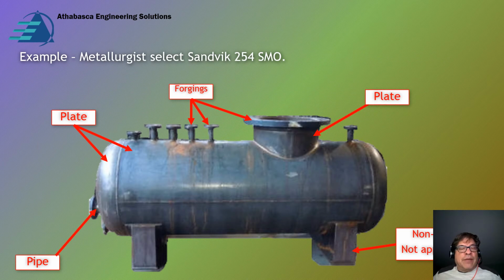We have our vessel, and we have to identify our product codes, and we call that the table I gave you earlier. So in some cases, our nozzle might be a fairly large nozzle. We might use a pipe, for example, and in other cases we'll use plate for sections like shown here, and for small nozzles we might use a forging, and for flanges we'd use forgings. And then plate, we might use a rolled plate for a very large nozzle. Now, at the end of the day, it's up to the pressure vessel fabricator to really choose what they want to do, because they need to get the lowest cost design which works for their particular facility.